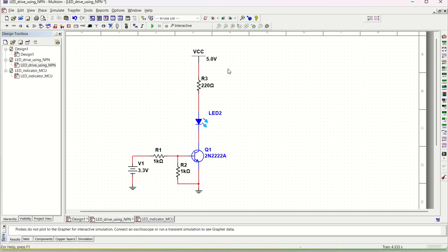As you can see here, we have a power supply. If you want, you can drive this by 3.3 volt also, not a problem. And this is the limiting resistor that we are going to use, that is our collector resistor. That collector node is there. And this is my LED that is connected in series, and this is going to be the driving signal or input voltage that is going to drive this particular transistor. Even a 1 volt signal will be able to drive it, and 1.8 volt also can drive this.